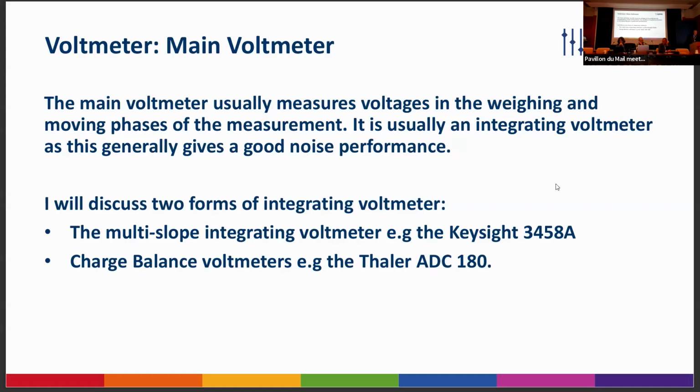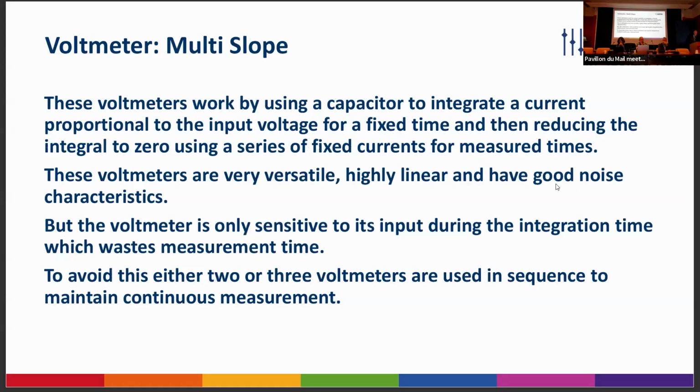But I want to talk a bit about charge balance voltmeters. Unfortunately, the Thaler ADC 180 is about the only commercial voltmeter that used charge balance techniques, and you can't buy them anymore. So we're building one. It was interesting that NIM in China, they're building the same sort of thing. I think once you've seen how they work, they're very, very nice.